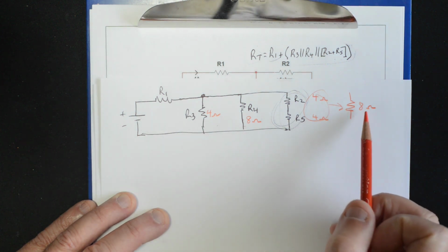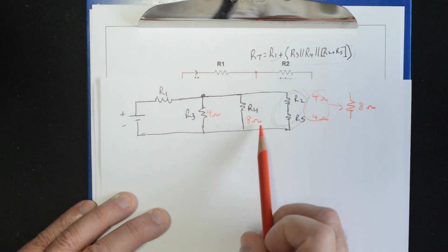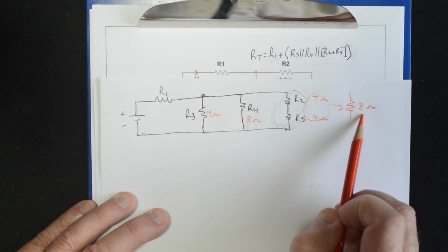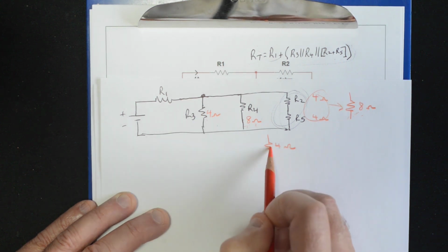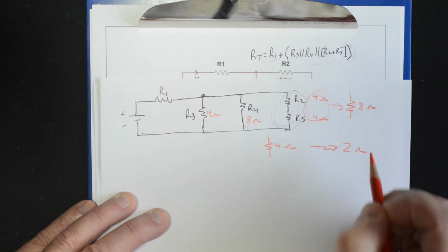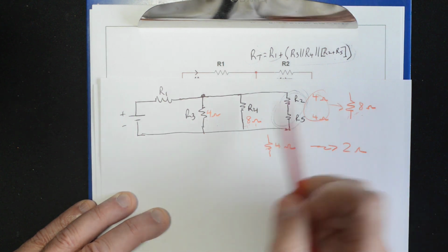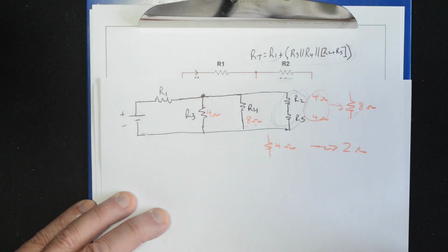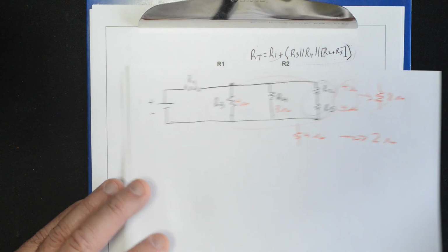But look at what we're dealing with here. 8 ohms in parallel with 8 ohms in parallel with 4 ohms. If you're looking ahead far enough, you recognize, put these two together first because they're the same. 8 ohms in parallel with 8 ohms is 4 ohms. And what do we have left? 4 ohms in parallel with this 4 ohms. We end up getting to 2 ohms. So you could do this in your head because, again, I did the numbers easily enough that you're choosing wisely. You never come out with any fractions or anything like that. This mess right here works out to 2 ohms.